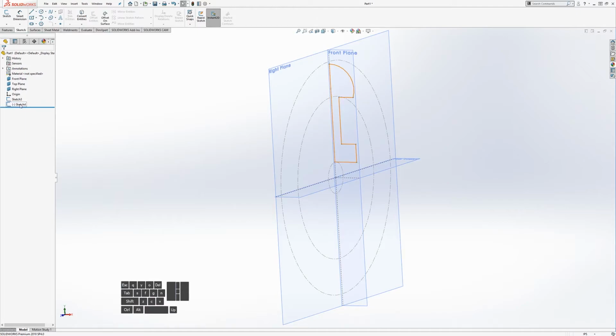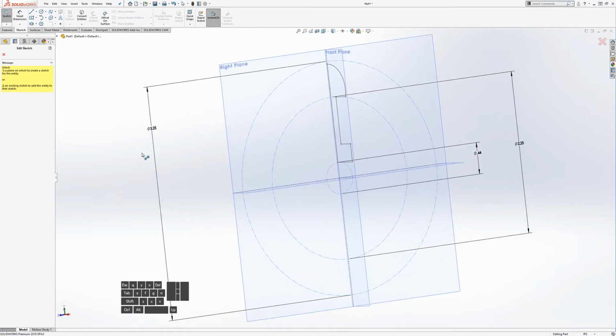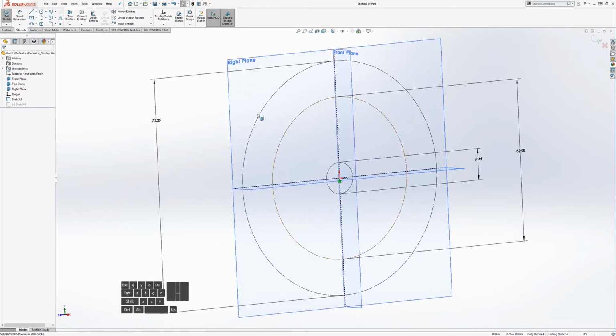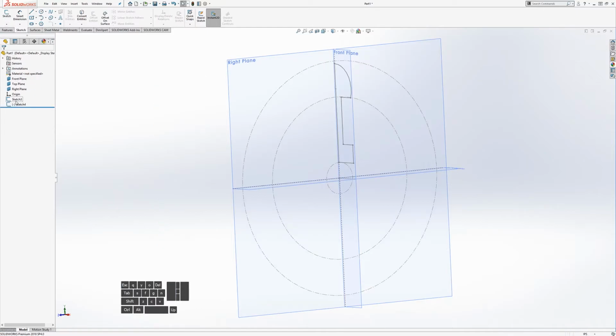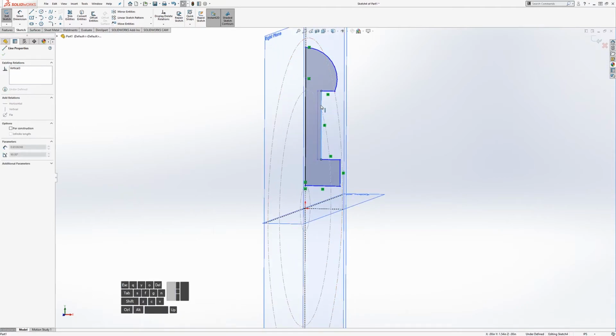That means that the sketch is unconstrained. Our previous one, if you go in there, get into the sketch, all the lines are black. They're all construction as well. That sketch is constrained. This one is not because it's blue, so that means there's some lines in here. So this line, the line is black, so we can't move it side to side, but the end point of the line is blue, so we can still move that around. And the other unconstrained geometry kind of tries to do its best to follow.